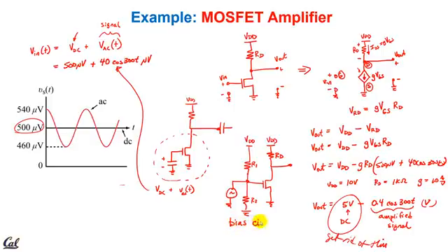Yeah, and this is called biasing. And there's lots of different tricks for biasing. This is a very simple one. You can do biasing not just on the gate, but you can bias all sorts of parts of the transistor. And again, if you like this stuff, there's lots of fun to be had digging in deeper and looking at the wealth of transistor topologies.